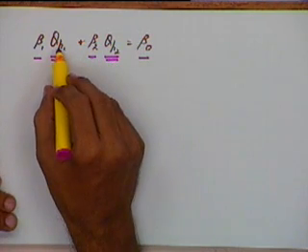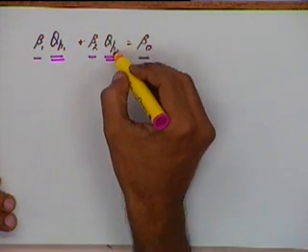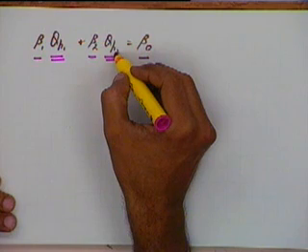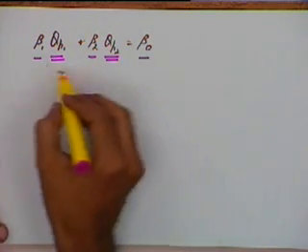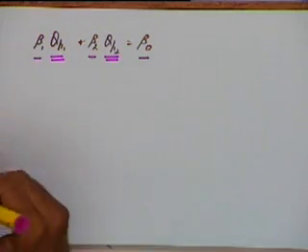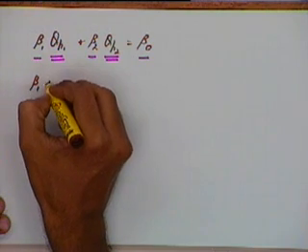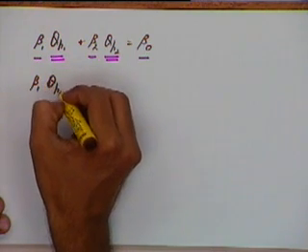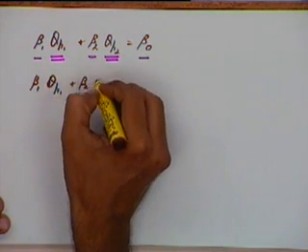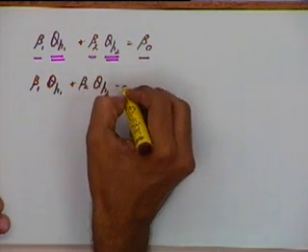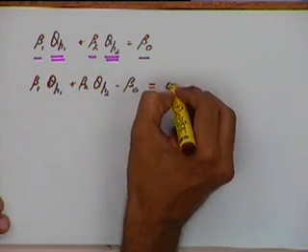QP1 is the deformation of node number P1, QP2 is the deformation of node number P2. If you have a boundary condition of this type, we will rewrite it like this: beta 1 QP1 plus beta 2 QP2 minus beta naught is equal to 0.